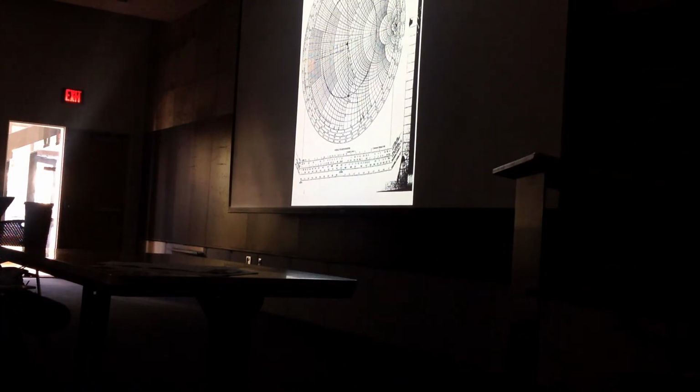So you see, step number one, identify the point of your normalized impedance on your Smith chart, take out your compass and draw this constant radius circle, and then rotate 180 degrees to the other side. You find your normalized admittance. Then this constant circle and the R equal to 1 circle are going to have an intersect: this point and this point.